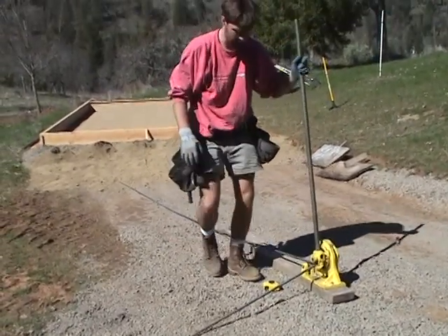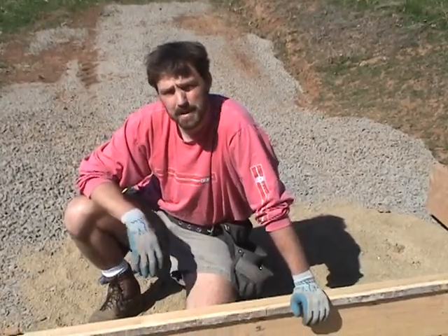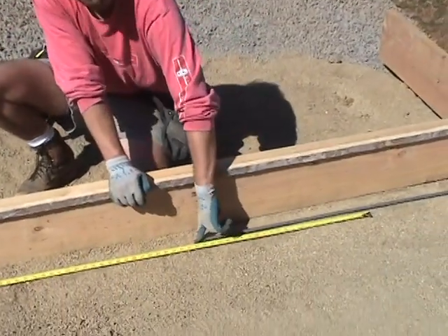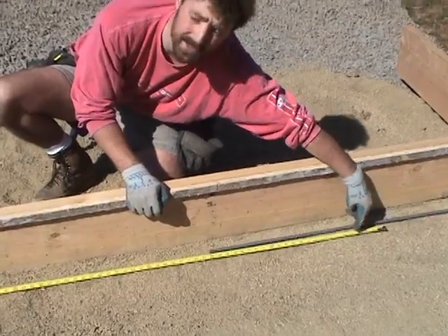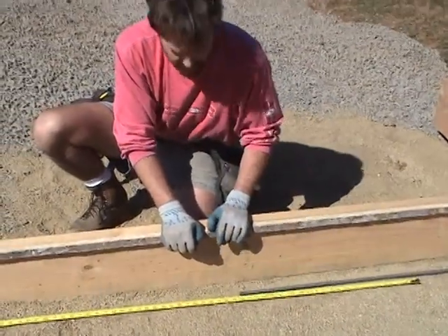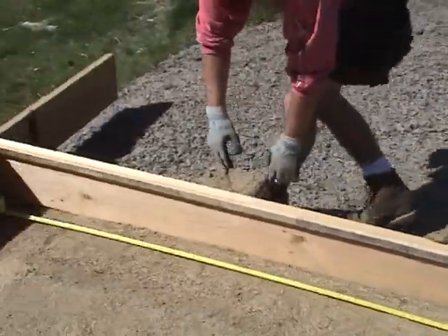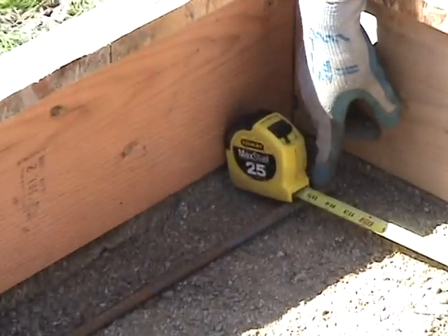There's your bent piece of rebar. So when we measure for our next piece of rebar, we need to be aware that we'll have to have a lap from the end of our last piece back over with our new piece so we can tie these two together. I'm using about a 2-foot lap here. As we come out along, we can measure down to the other side where we need to place our bend. In this situation, it's 115 inches.